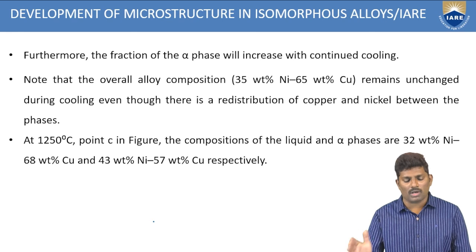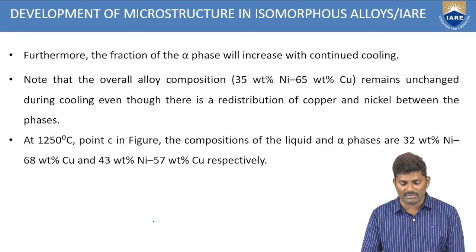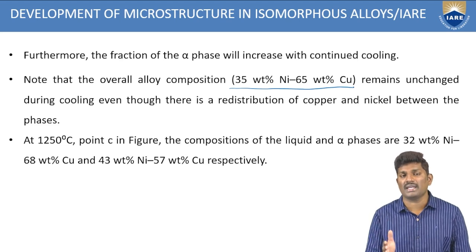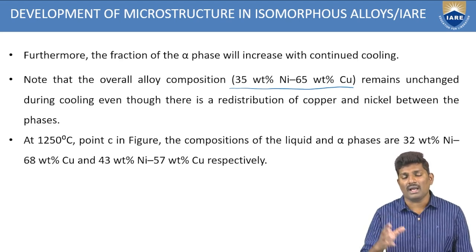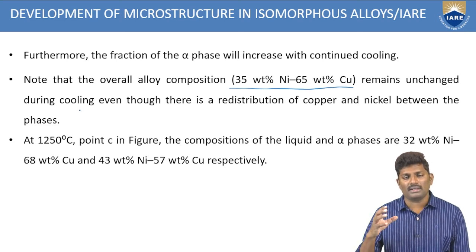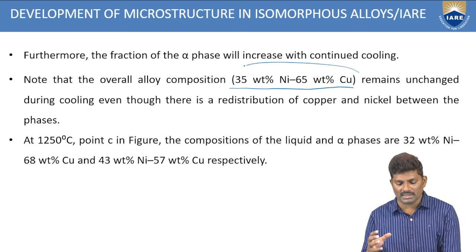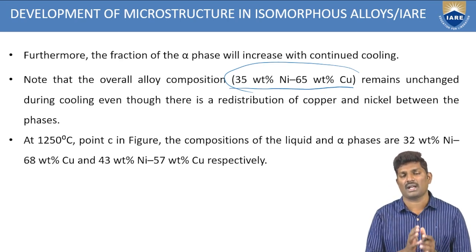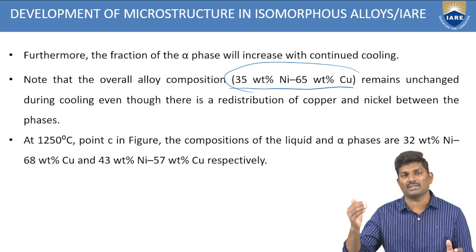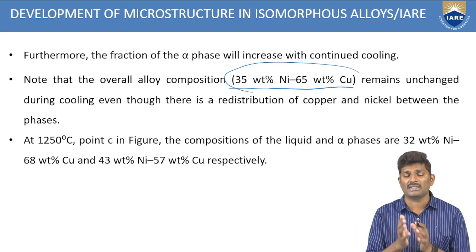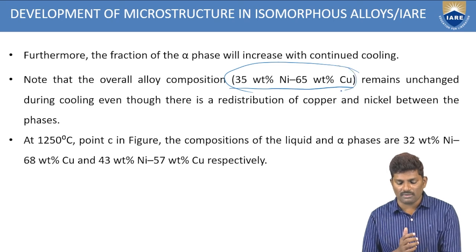Now, the overall composition of the alloy that we have taken here is 35% nickel and 65% copper. So this remains unchanged until what point? Until the liquid nature. Until the liquid nature, this composition will remain unchanged. But when the cooling starts, what is happening? There is a reduction in the temperature, and because of this reduction in temperature, there are changes in the composition. So this composition will change now.